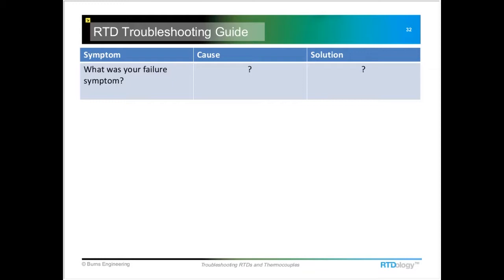Okay. And then we've got a somewhat similar question. They've got an RTD that seems to work fine when it's at temperature, about 150 degrees C. But once they shut down the process, the next time they start up, it doesn't seem to be tracking until it's been up to temperature, 150 degrees again, for some amount of time, and then it seems to stabilize. Yeah, the first thing that comes to mind is that it's an insulation resistance thing.